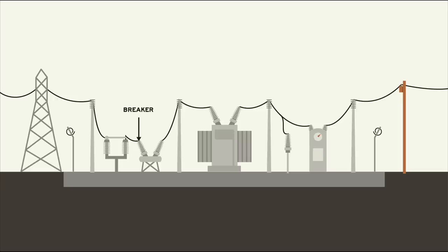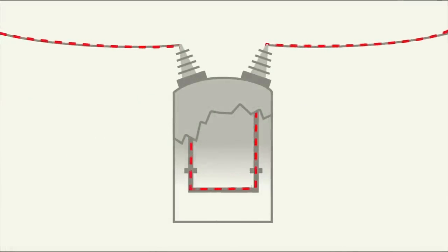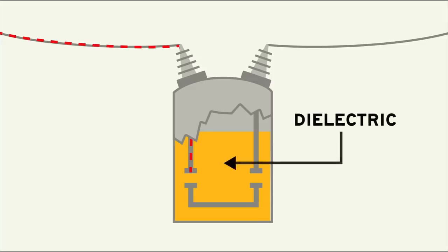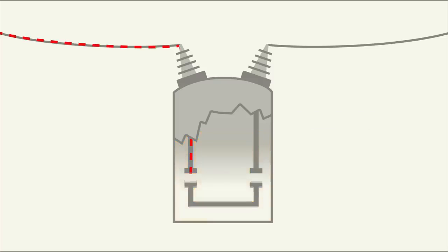On the other hand, circuit breakers are a class of device that serve similar roles as fuses, but provide more sophistication for dealing with a wide variety of faults. Like disconnect switches, circuit breakers need to be carefully designed to interrupt huge voltages and currents without damage. As soon as contacts within a circuit breaker are moved apart from one another, an electrical arc forms. This arc needs to be extinguished as quickly as possible to prevent damage to the breaker or unsafe conditions for workers. Extinguishing the arc is accomplished by a material called dielectric that doesn't conduct electricity.